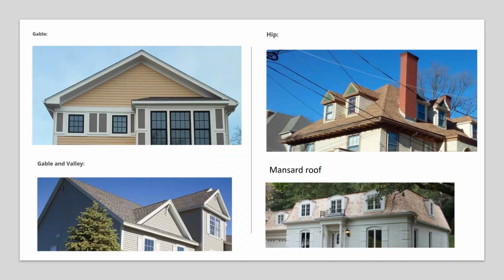These are different kinds of roofs. This is a gable, and it's important that you understand a gable roof, because you're going to have somebody mention in a home inspection report a gable vent, and that would sit in here. If it had a gable vent, you know it's got a gable roof. This is a hip roof where you've got 4 different sides all coming together in one short chute over here.